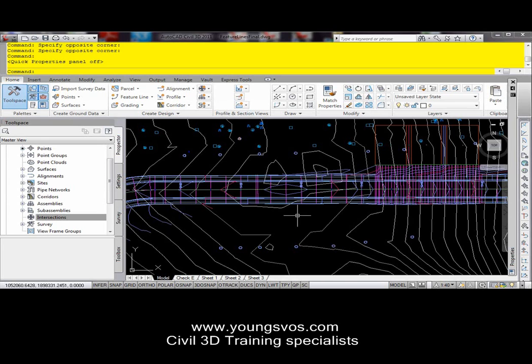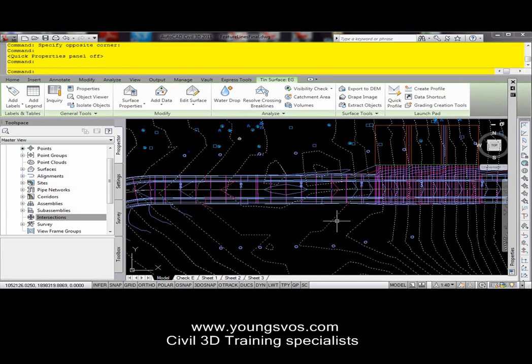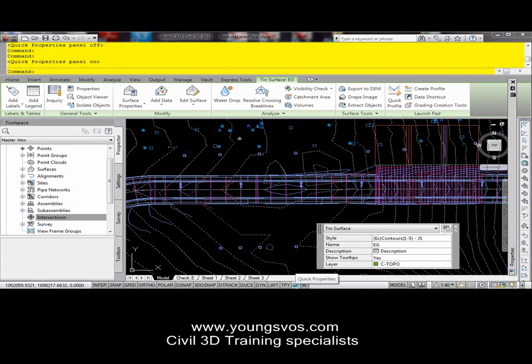All right, so what you see on the screen here, of course, is a surface and a corridor. And today we're talking about this thing down here called quick properties. Now, normally if you select a surface, you're not going to see anything. It's just selected. If you move over here, of course, you're going to see a couple of other things, like, for example, the station and offset at the top there for the street and the elevation at that particular point for the surface. If I turn on this quick properties, you can see some additional properties for the item I've got selected.